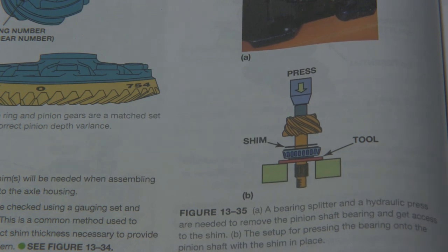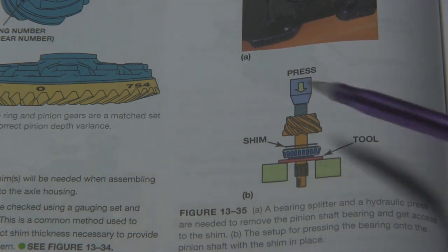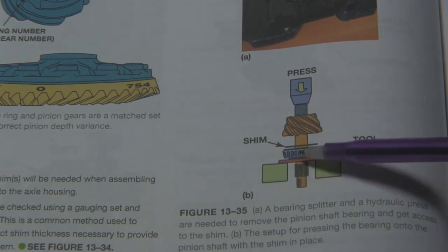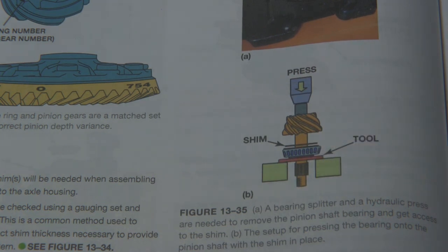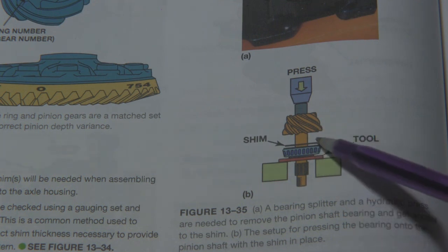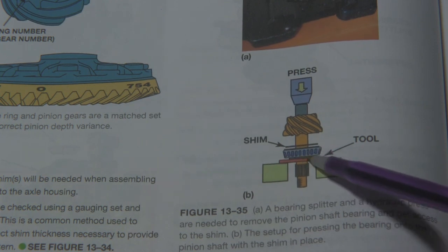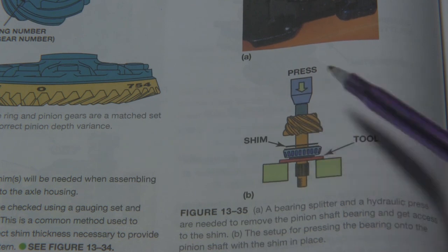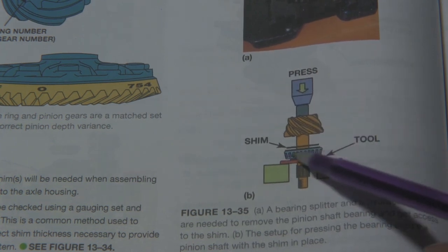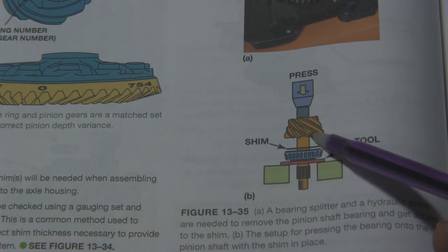And so one of the tricks that rebuilders will do is they'll have an extra set of bearings. And now I don't mean you have to go buy a second set necessarily every time you rebuild an axle, but let's say you do a lot of rebuilding and you do a lot of the same type of axles over and over and over again. A good idea is to take a new bearing, and then literally take a Dremel to the center of the bearing and wallow it out and remove the press fit. So that way this bearing simply slides over that shaft.